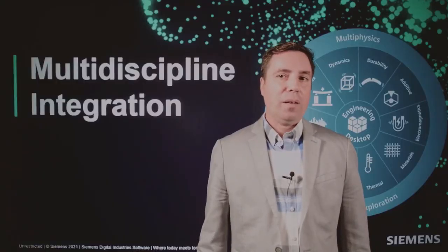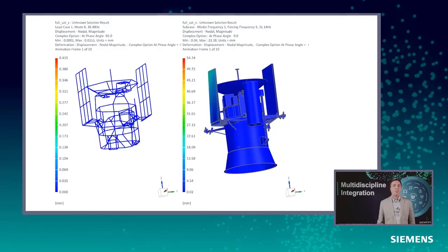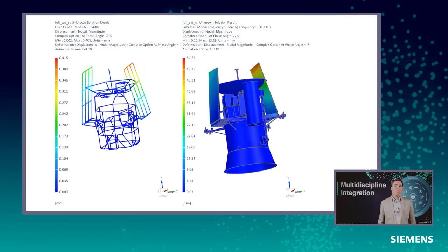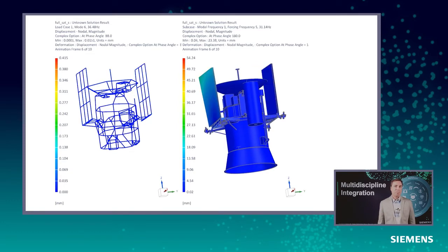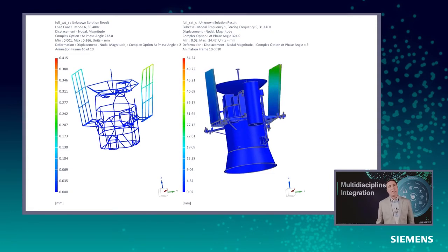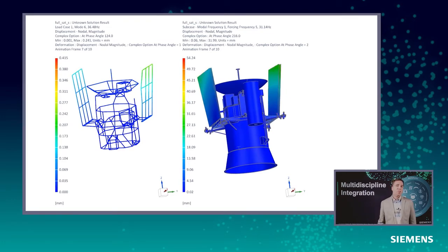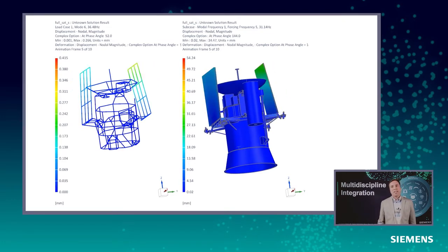Comparing operational responses with mode shapes can provide valuable insight into the degree of participation of one or more modes at key frequencies, especially in the presence of closely spaced modes. For example, you can identify the modes and frequencies of the standalone antenna in the vibration response of a complete spacecraft. Comparing test and analysis operational shapes can calibrate the FE model when mode shapes can't be obtained. Comparing two sets of operational shapes can shed light on the effect of different loading conditions on key responses of the structure.